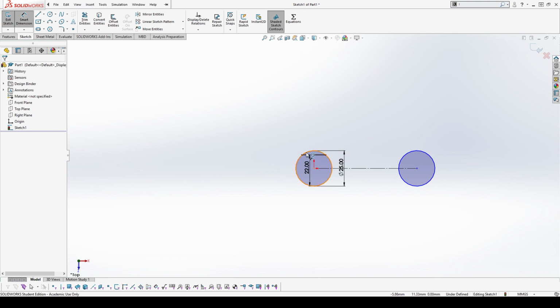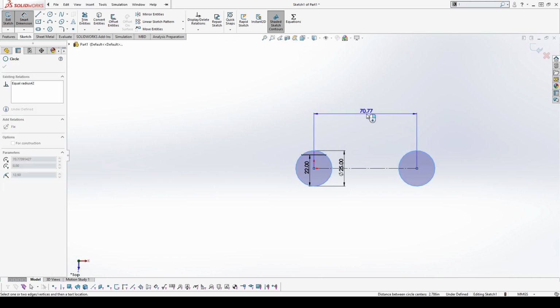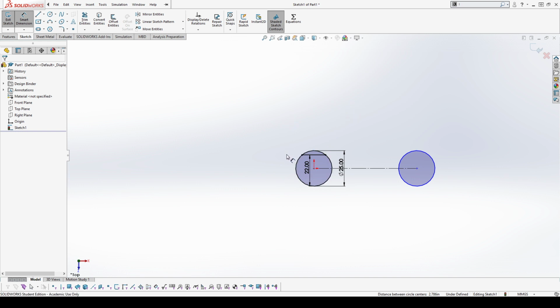If I click these two circles, and I don't want to do extra math that I need to, I'm an engineer, I'm lazy. That's just to make it easy. It was 100 millimeters between the outside edges. These are 25 millimeter pieces, so it should just be 75 millimeters, right? But again, I wanted to reflect how I measured it, and my design intent.